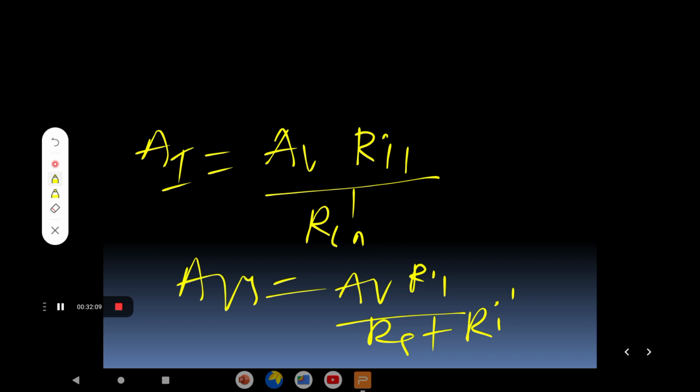After that you have to replace it with the small signal model, or we can also call it the mid-band AC equivalent circuit. That is nothing but connecting the supply voltage to ground and the capacitors to short circuit. Like that you will get the same analysis whatever we did in the case of the BJT. So you will follow the same process as we discussed in the previous case, just with small changes in the formulas.